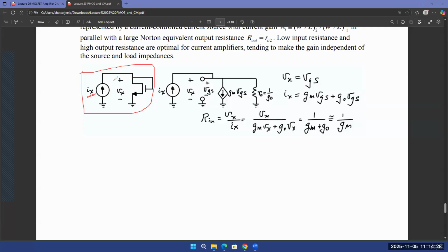So if you want to analyze just the AC current, okay, so let's say I have an AC current source going to the drain of this diode connected transistor, which is on the left side of the current mirror. So let me draw the current mirror circuit over here. You have a diode connection here, you have a current source coming from the top, and then you have another transistor on the right side. So basically, whatever current is here, let's say this is I1, I will be forcing a current I2, which is a function of I1. So the current I2 will be a function of I1. And if the widths or the lengths are equal, then I2 will be equal to I1.